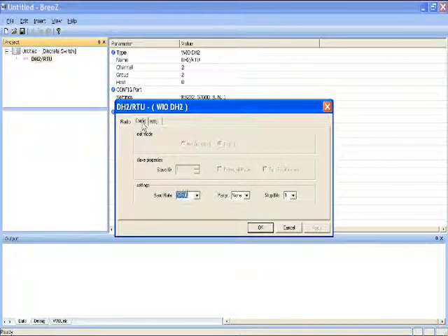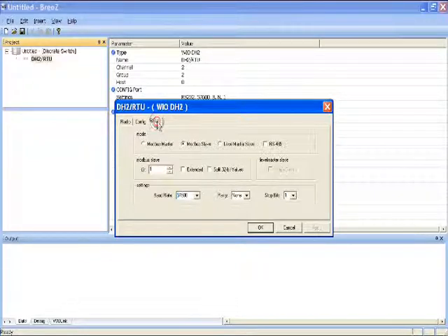The Communication tab is signifying the RJ jack in the back of the DH2. Then go to the RTU tab. This is signifying the 6-pin Phoenix connector in the front of the DH2 that you can wire for 232 or 485. If wiring 485, check this box. We are a slave to the master. ID the slave, other than 1 if needed. If you need extended register addressing, you would check this box. If you needed to split 32-bit values in your RTU, you would check this box.